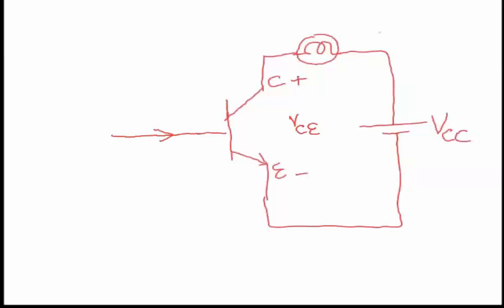Let's say you have a voltage of at least 0.7 on the base, correct? Yes, you require two voltages. One is from the base perspective, which decides whether the transistor is going to be on or off. Second, you require the collector voltage to turn on whatever load we are working with. The load could be a lamp, a motor, or a speaker. You require both voltages. But how do you provide them? That's up to us. But you require two voltages.